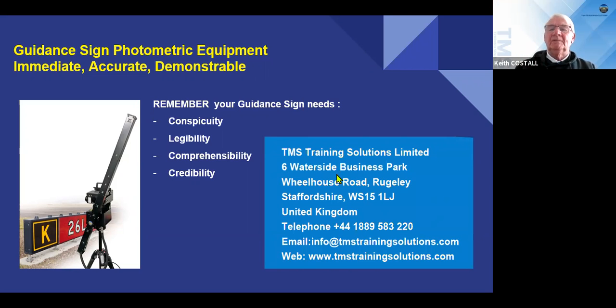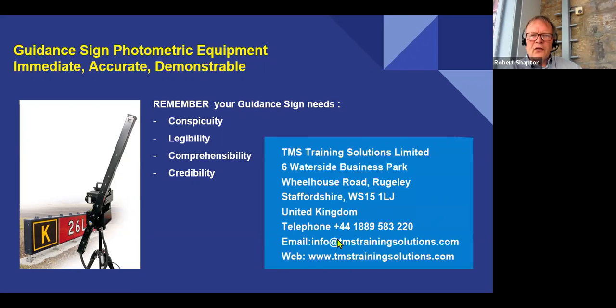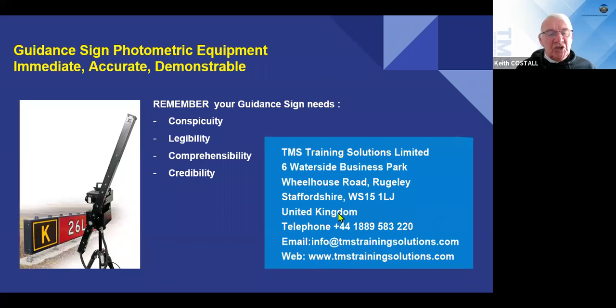Our good friend Bart Marischal would like to know: do guidance signs need to be installed level, or can they follow the shoulder or turfing slope? That's a very good question, and it's come up several times. We're talking about the mounting, aren't we?